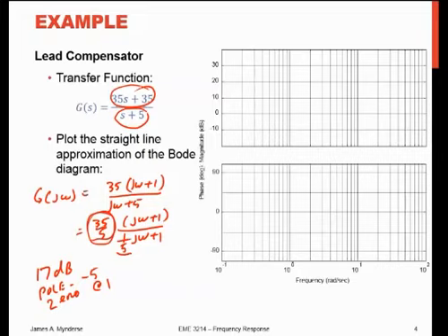And if you remember, going way back, the final value theorem in Laplace domain, as time approaches infinity, s approaches 0, right? So as time goes to infinity, these terms go to 0, and I'm left with my steady state gain there of 35 over 5 if it was a step response. And you get the same gain in frequency domain. Okay, well, because at low frequencies, essentially that is just the response to a simple input.